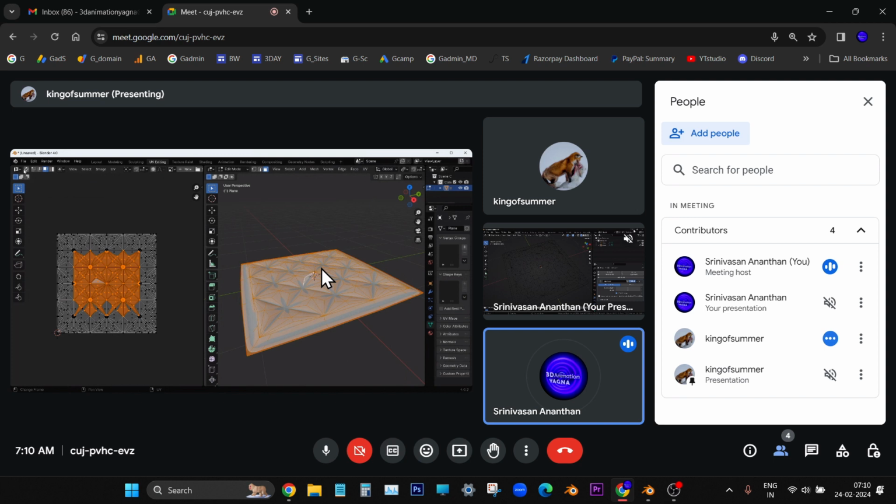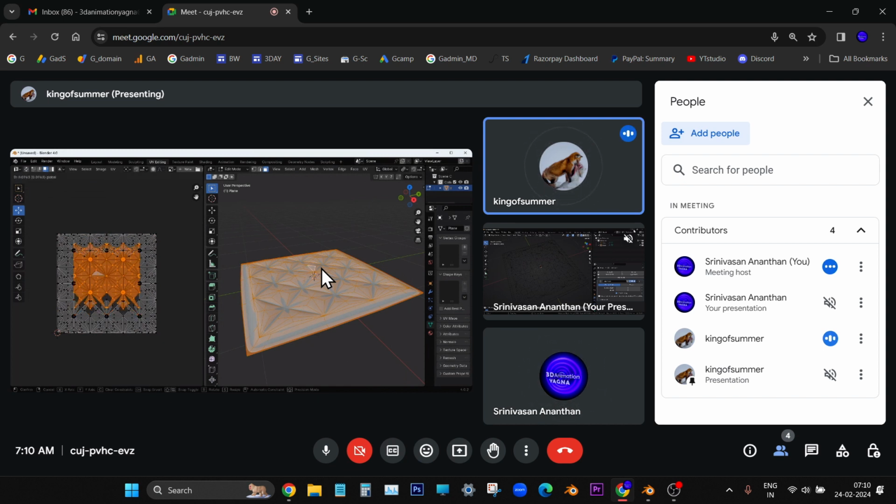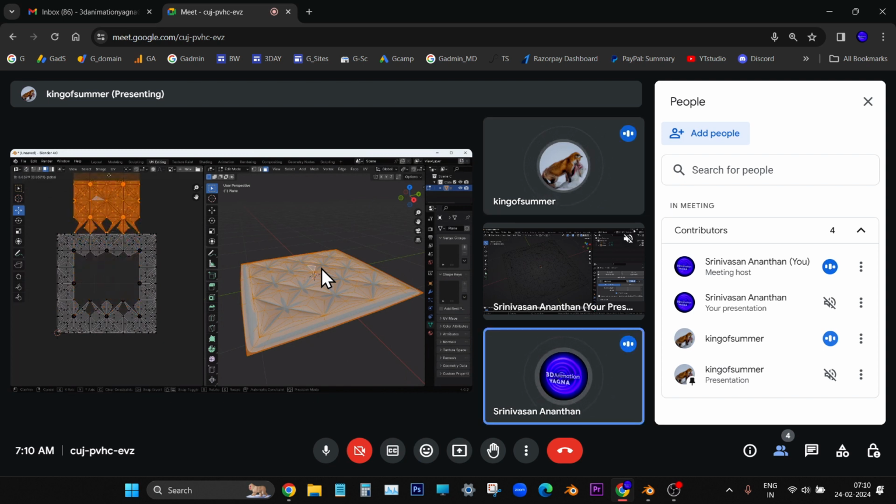Now faces. No, switch off the sync button. Choose the move handle in the toolbox and just move it. See, it will come like this.